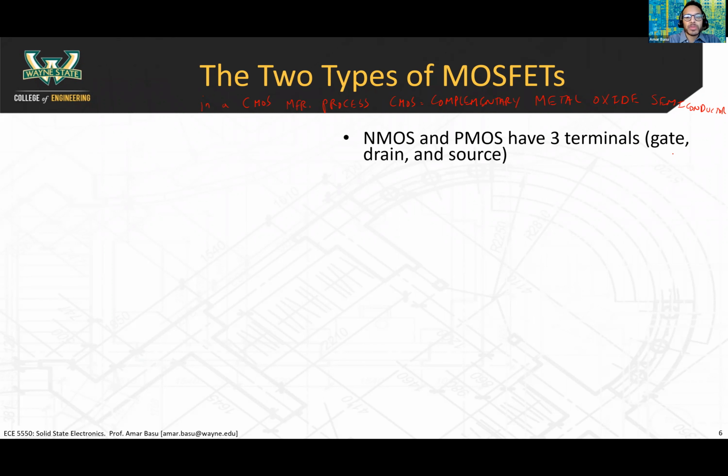You probably heard that term CMOS because it turns out that the CMOS manufacturing process, which has been developed and optimized over 4 or 5 decades now, allows you to make both NMOS and PMOS devices in the same manufacturing process. And having both of those turns out to be very important for the two functions of MOSFETs: the digital switching, which is used in logic gates, and also analog amplification, which is used for wireless radios.